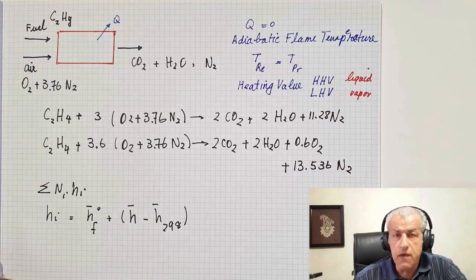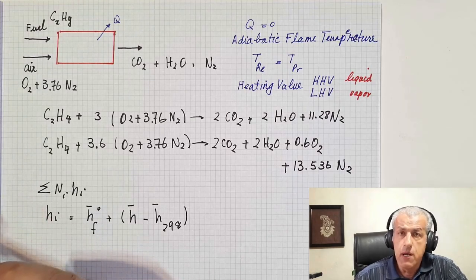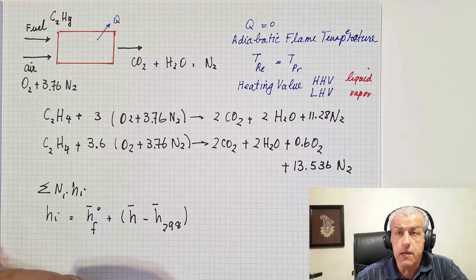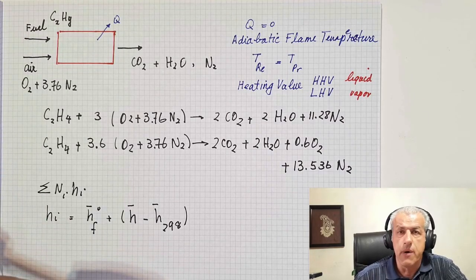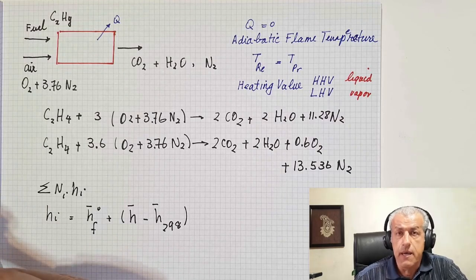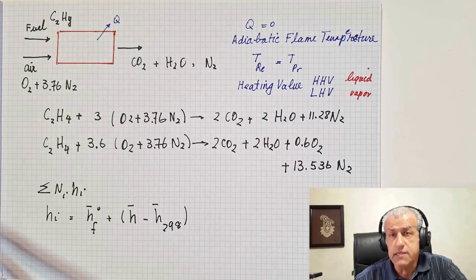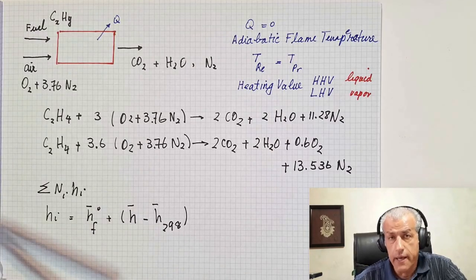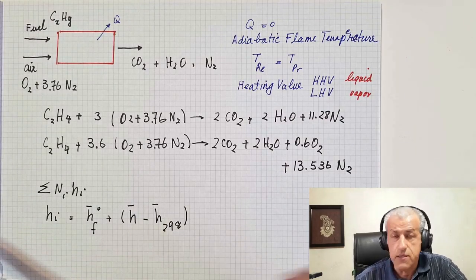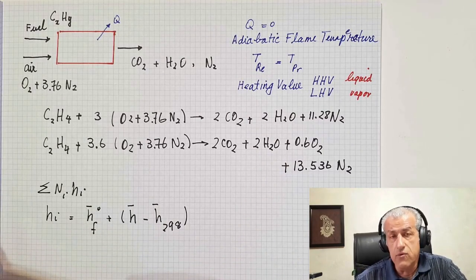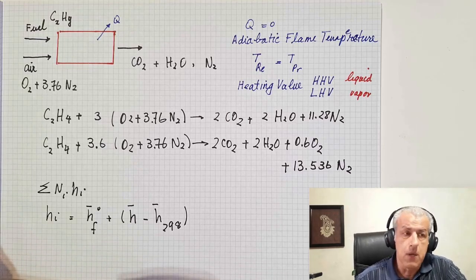But if there is, say, a boiler, then the boiler is an external combustion equipment, and therefore the gas should lose its heat to water, and the more it loses, the better it is. So a higher heating value would be more appropriate as the ideal heat that we could collect